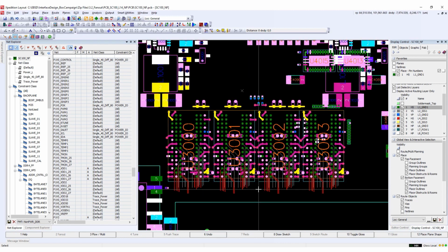So I've now completed the fan out and breakout process for all 4 of the DDR4 ICs on the board. The SIPI engineer Rory can now begin defining the decoupling strategy and analyzing the power distribution using HyperLynx. Once this analysis is complete, Rory can make suggestions to the hardware engineer Nicole, who will make any recommendations to the schematic and forward annotate those edits. Once a forward annotation bundle is ready, I will import those changes back into the layout and update the parts.